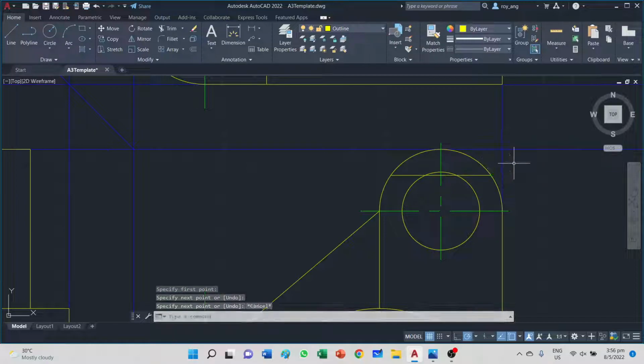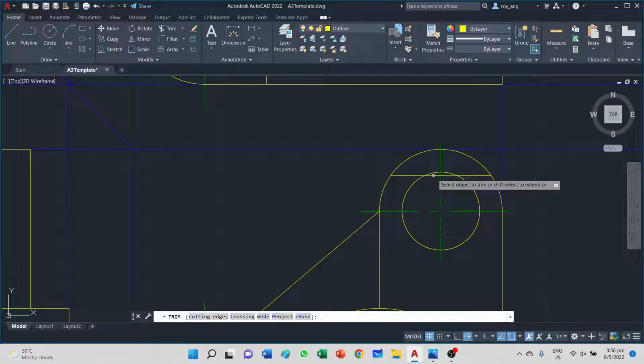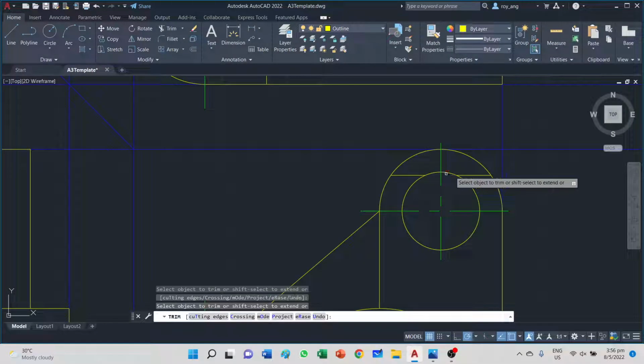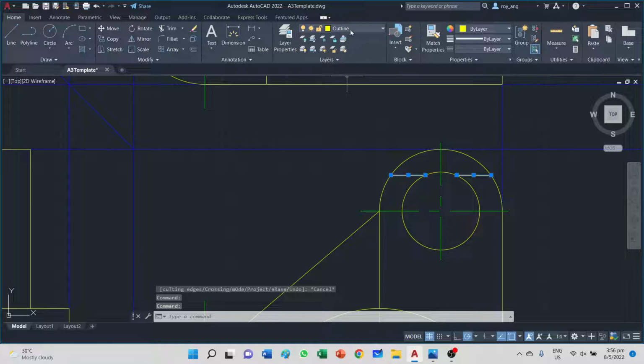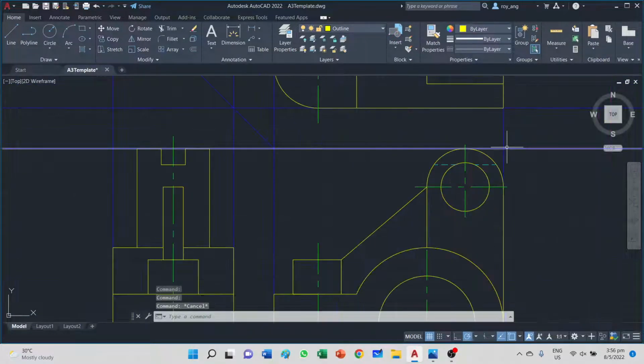However, over here it passes through the hole. Because it passes through the hole, the center segment here is not reflected, and these lines are going to be the first hidden lines that we'll be drawing, and we'll start our hidden line journey.